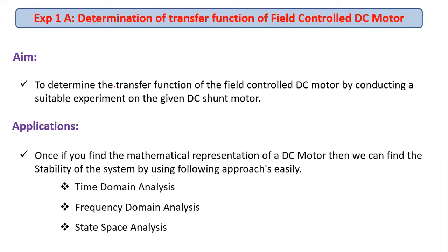Coming to the constants, what are the constants? In mechanical system, torque constant is there. In electrical system, back EMF constant is there. Once we know all these 6 parameters, then we can write the transfer function. We can identify the transfer function of field control DC motor.